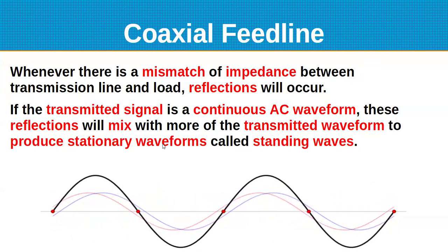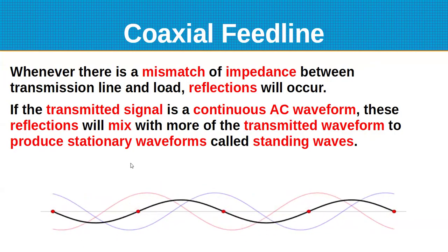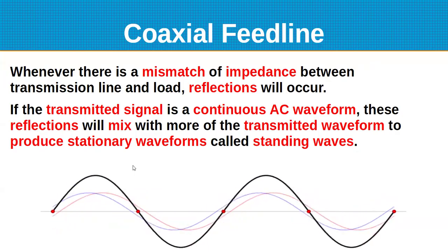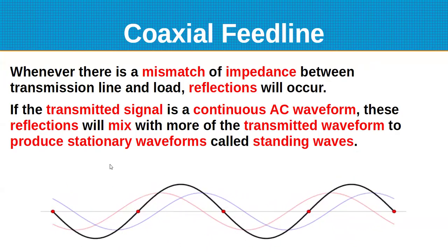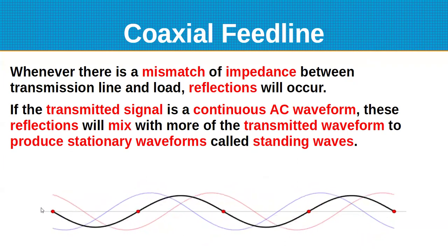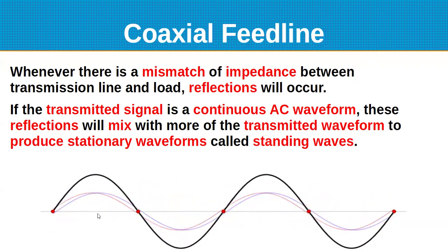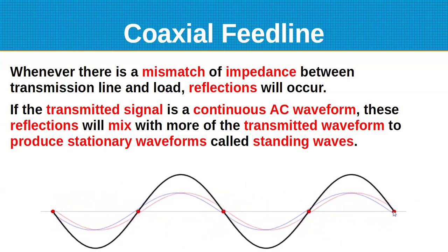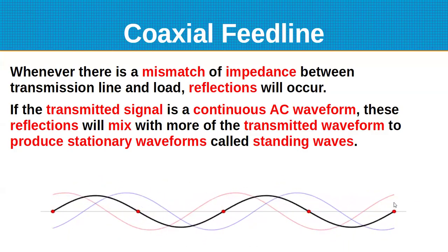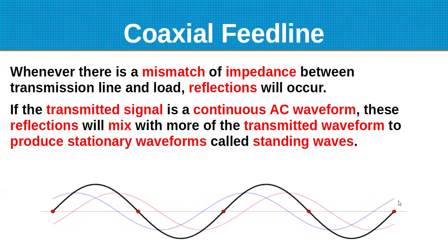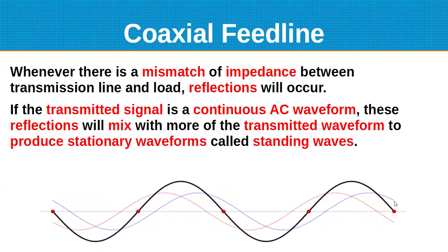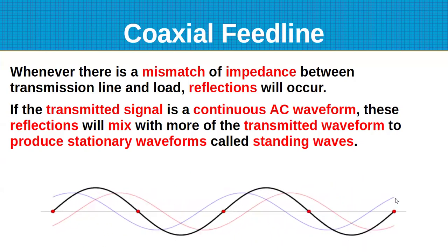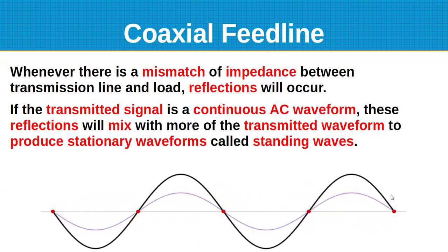And if you look at the animation, I'm assuming everybody's seeing these. Yes. The blue line is representing the signal that's being sent over the transmission line. When it gets to the antenna, because there's a mismatch, it's reflected in opposite polarity, 180 degrees out of phase. So that's the red line coming back.